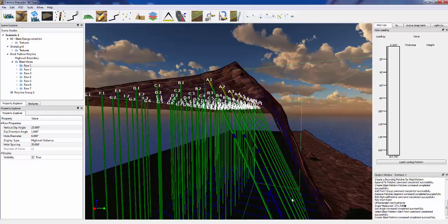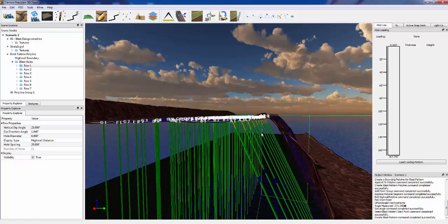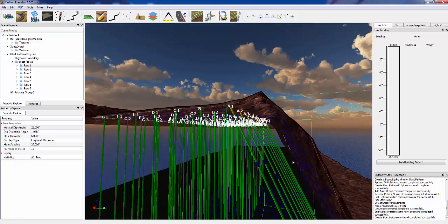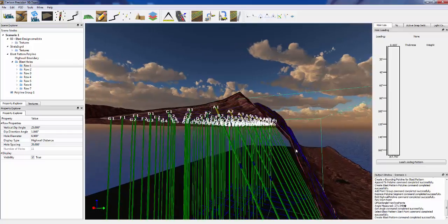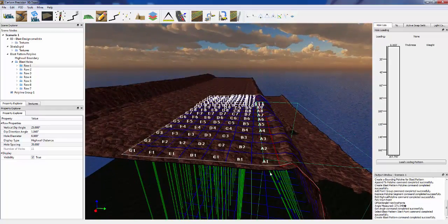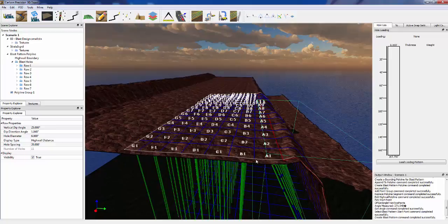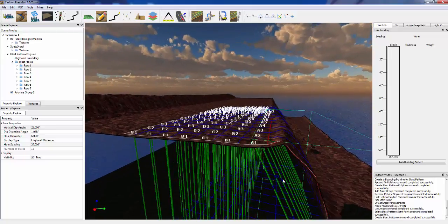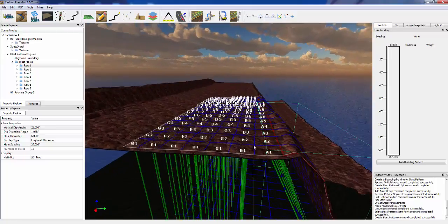And again, now what you're seeing down along in here is we're showing you that you're still within your 10 feet, but there's still some blue spots where you're almost half the distance away from that particular point. So you can see there's a little bulge here, and as we project this straight out, there's a little bit more distance covered right in here. But again, we'll give you that visual indication. So if you need to modify your hole loadings for these particular holes, you can do that.